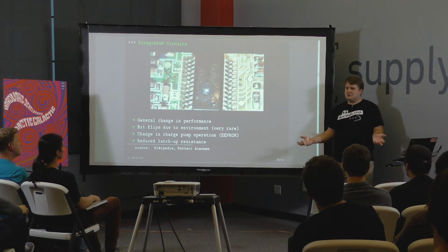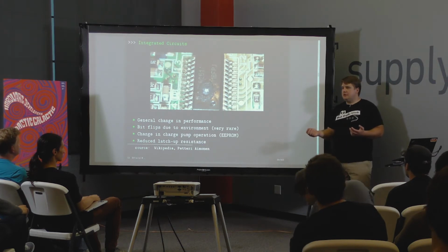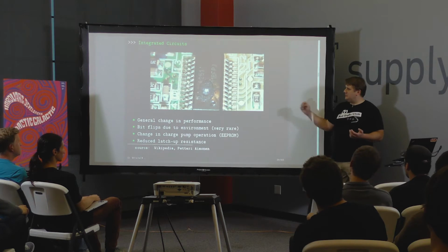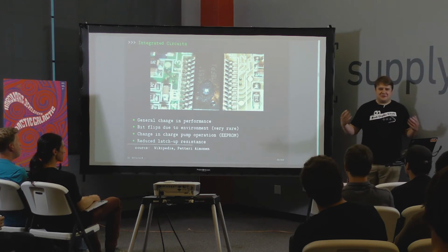But in some situations, if you can create lockup in your device, that can be catastrophic, and you want to make good use of watchdogs, because generally speaking, if it's up there and something is not responding, just power cycle it. Then design it such that you can keep power cycling stuff until it gives you the thumbs up.